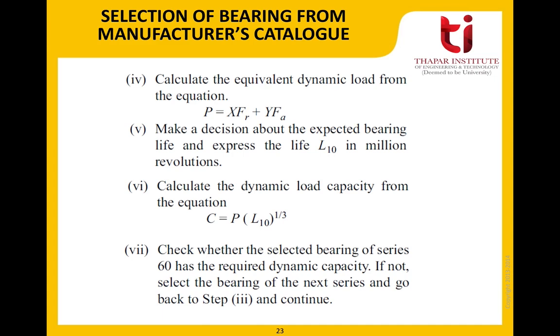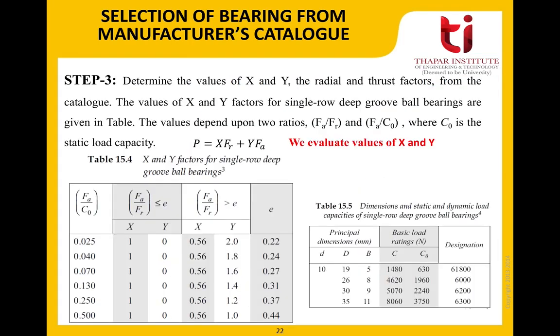Again, you need to note down a point that the series 60 corresponds to deep groove ball bearings. We have gone for the 60 series here, just to give you a hint that most of the tables that are provided in VB Bhandari correspond to single row deep groove ball bearings. But there can be numericals or questions from other series designations or different types of bearings as well.